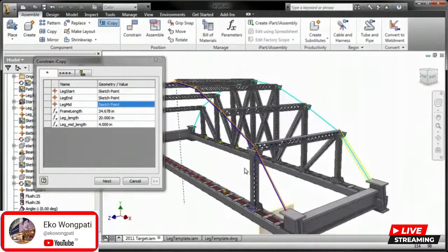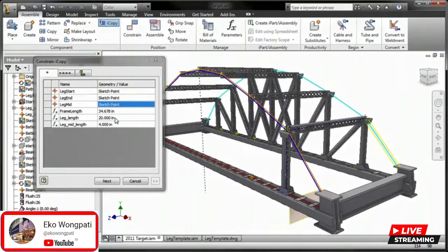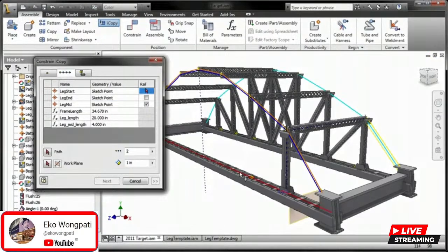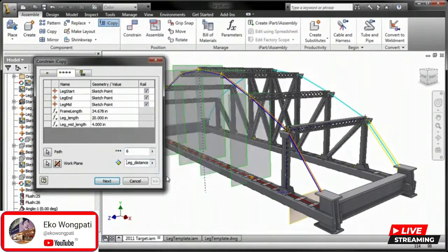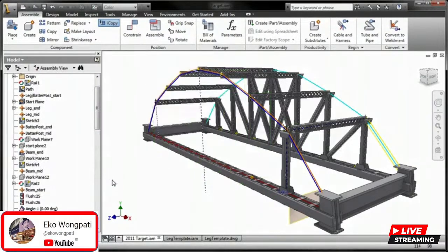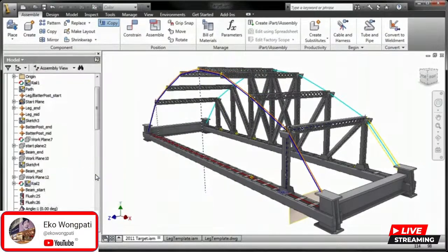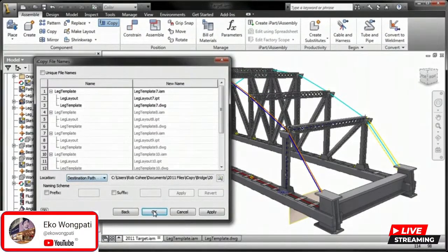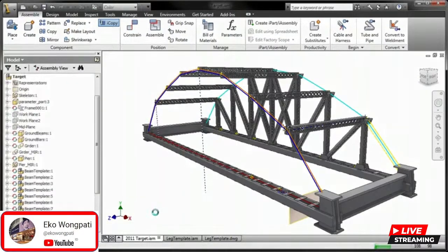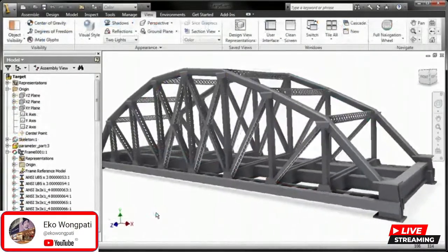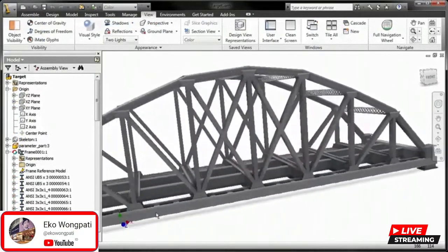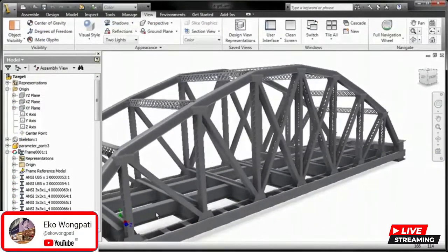iCopy automatically resizes multiple copies of standard elements to fit within a design by referencing a few key constraints such as connection points and paths. iCopy combines skeletal modeling and adaptability, allowing the subassembly to change in order to fit its position in the model. And because your 2D drawings in Inventor are associative with the 3D model, the drawings of each copied subassembly get updated automatically. iCopy can save valuable time for engineers who need to explore multiple design iterations of structural elements quickly.